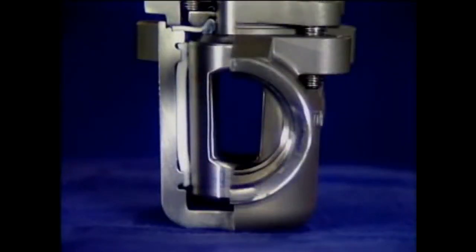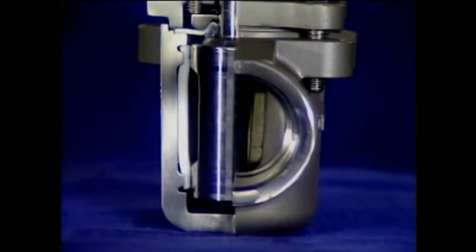For complete shutoff of fluid flow, the plug and seat must make a close fit as the plug turns in the valve body. The close fit is needed to avoid leakage around the plug. But because of this close fit, turning the plug can gradually wear out the plug and seat. If either one wears out, fluid flow won't be shut off completely when the valve is closed. To minimize the friction between the plug and the seat, many plug valves are lubricated. Some plug valves are equipped with a fitting on top of the stem through which lubricant is supplied to the plug. Now let's take a look at another type of plug valve, the multi-port plug valve.